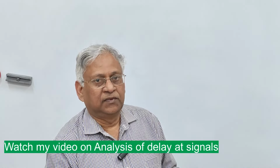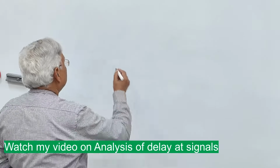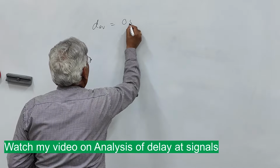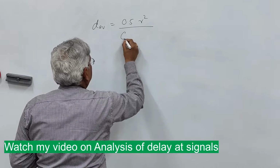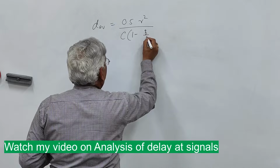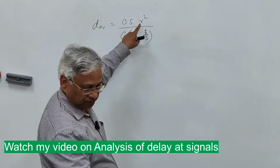Now, this is based on signal design. What is the average delay at a signal control intersection? And again, if you know the equation, then average delay is given by this equation: dA is 0.5 R square upon C into 1 minus Q upon S. R is the red time.